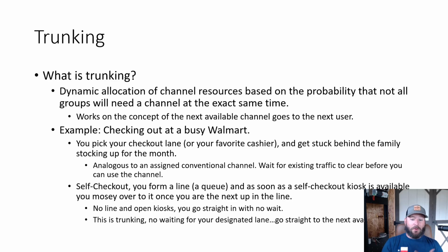So back to our whole EMS scene needing to send an update. Well, fire's using the channel currently and they're talking. Well, as I already said though, PD's not using it. Well, a trunking controller would say, hey, use the PD channel to send your message. And you'll get your message through. PD doesn't need it at the moment, and the message goes through. That's trunking in a nutshell.